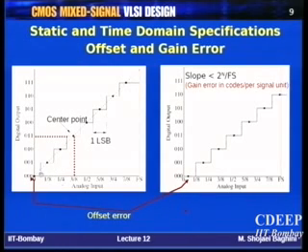So you expect the trigger point to be exactly here, which is half LSB, but actually it will happen a little after that. Suppose offset is constant and remains fixed, it is just like you have shifted your plot or curve to the right, right? Because now effectively all your switching points have been shifted to the right because of the comparator offset.